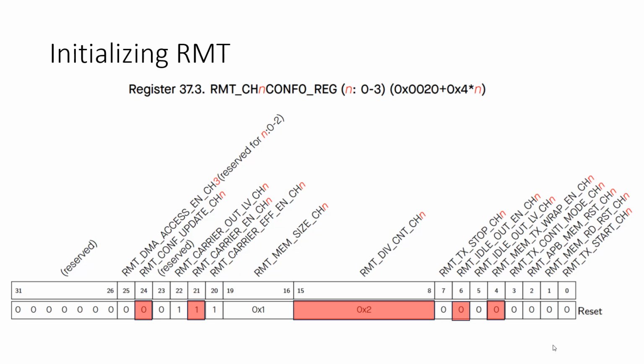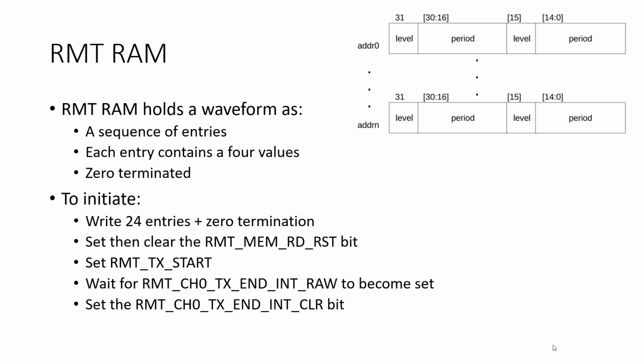We had a config 1 register, but one of the changes they made in the ESP32-S3 is they dropped config 1 for channels 0 to 3. So in case you see any reference to config 1. And there is a config 1 for the LED peripheral too, by the way. So that's another reason that might be confusing. Okay, and by the way, the reason for config 1 and config 2 is just so we can have 64 bits of total configuration bits, because there's only 32 bits per register.